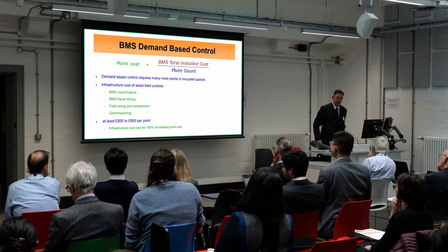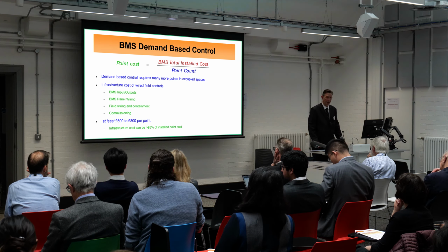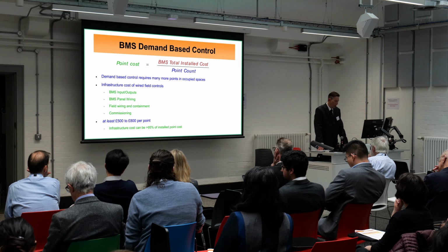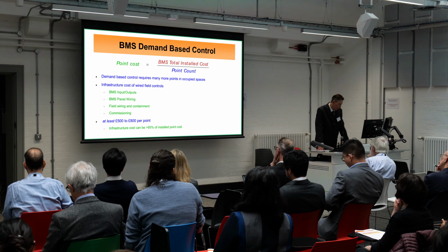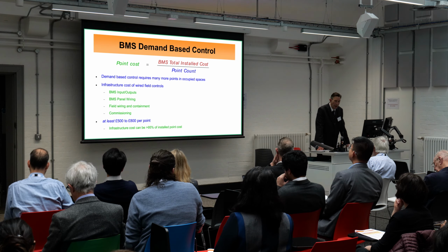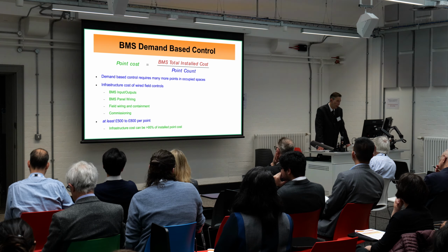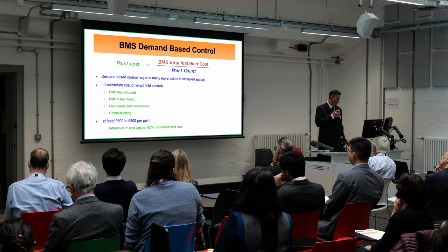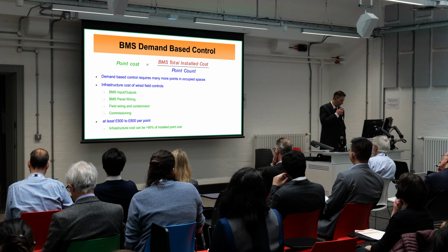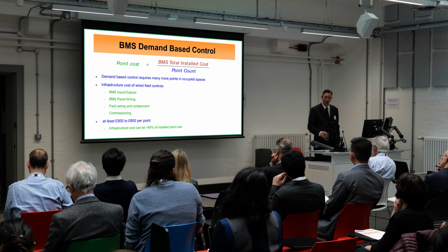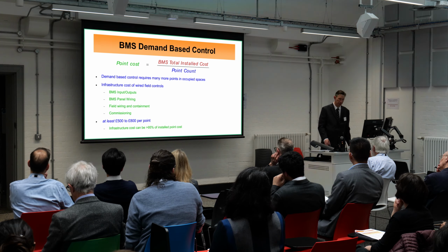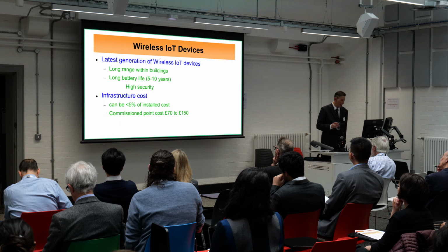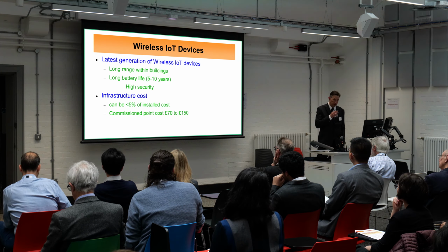And if we're looking at any sort of cost-benefit analysis, we don't have to think too hard or do any detailed analysis to realise that putting in hundreds of sensors is not going to be justifiable as far as the payback is concerned. So one of the obvious things to do is say, well, if our infrastructure cost is so high, let's get rid of the infrastructure. And so therefore one of the potential solutions is to go wireless.